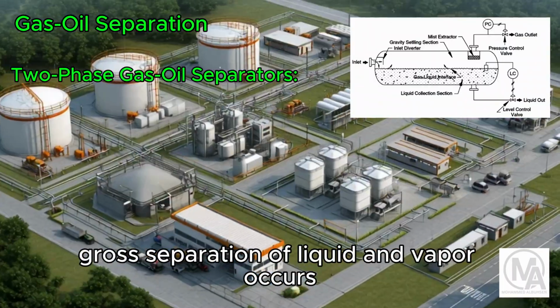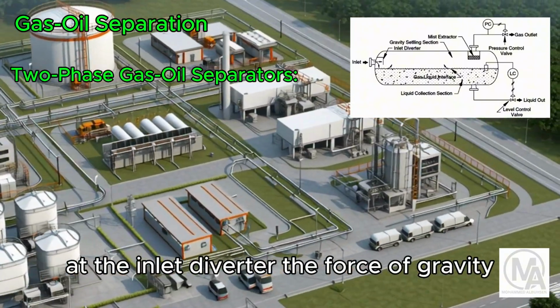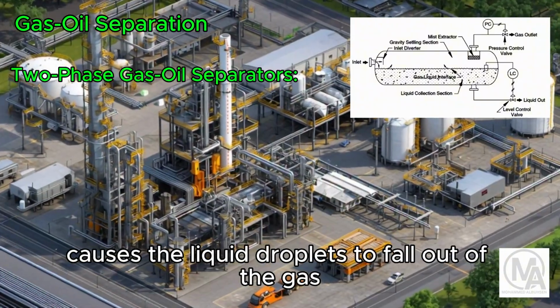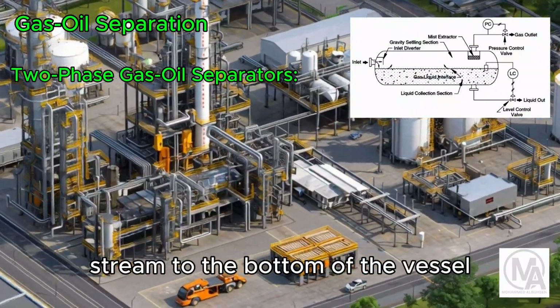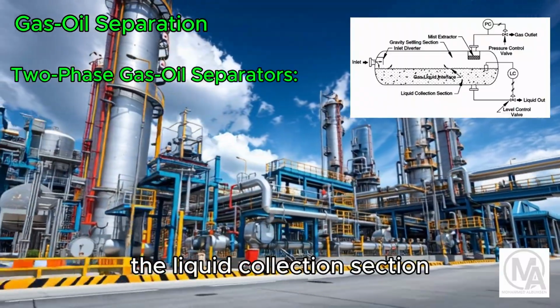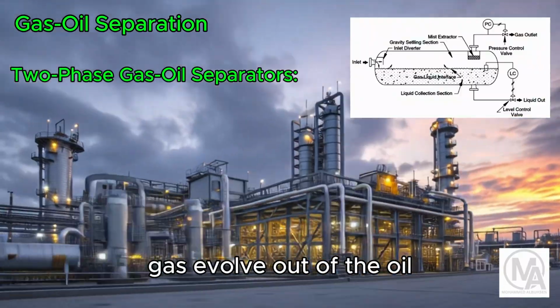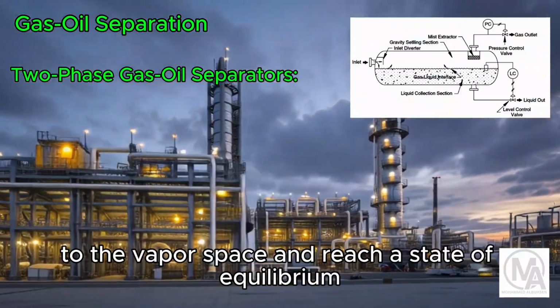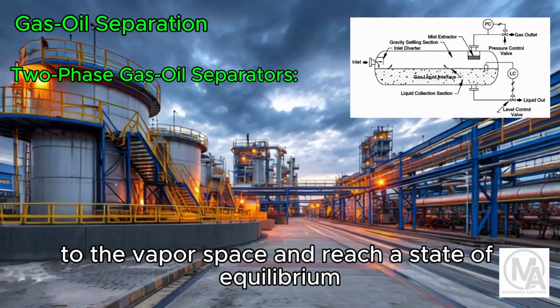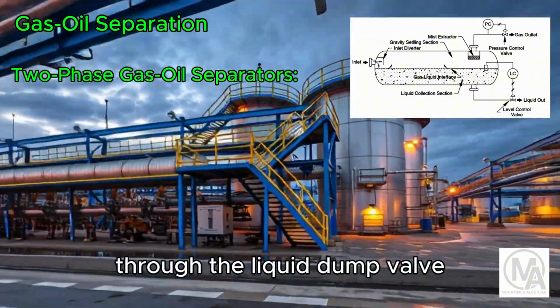The initial gross separation of liquid and vapor occurs at the inlet diverter. The force of gravity causes the liquid droplets to fall out of the gas stream to the bottom of the vessel, where it is collected. The liquid collection section provides the retention time required to let entrained gas evolve out of the oil and rise to the vapor space and reach a state of equilibrium. The liquid leaves the vessel through the liquid dump valve.